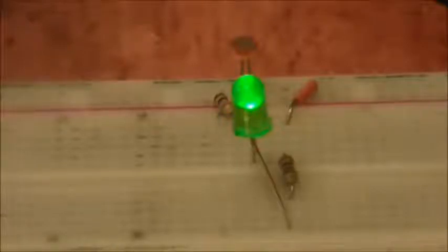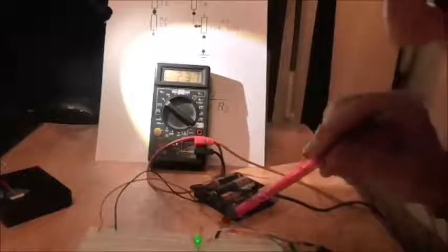Well, I think what we could probably do now is put a multimeter on there and see what we get. What we have here is this multimeter reading, with reference to ground, which is here, the output voltage at the junction here. I'm not quite sure how clearly you can see it on the camera. Looks alright in the viewfinder, but it says 2.36 volts. Well, it's flickering between 2.36 and 2.37.